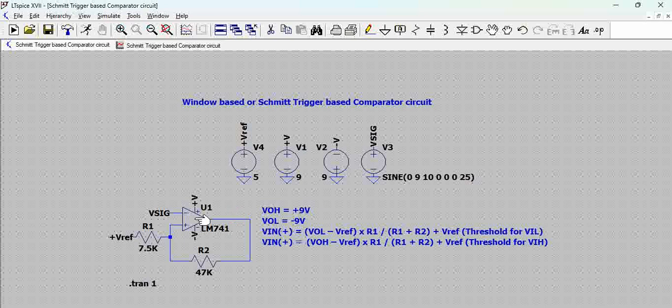You can check your model, and also the input impedance of this particular op amp is considered infinite. So these are a few assumptions that are considered, but at least the signal is what we can include. The LM741 parameters are part of its model, but for the signal related part, in case you want to add a series resistance to emulate the signal output, the supply output impedance, we can actually do that.